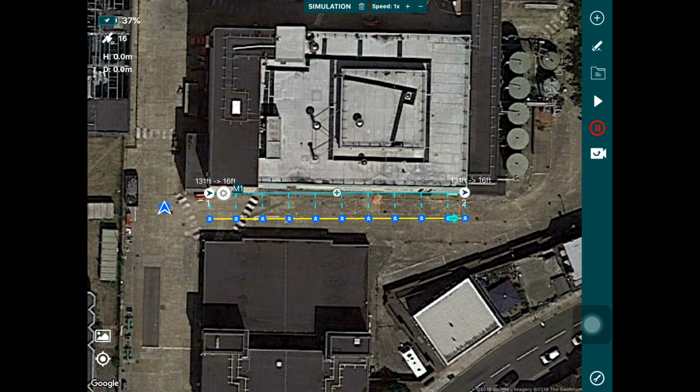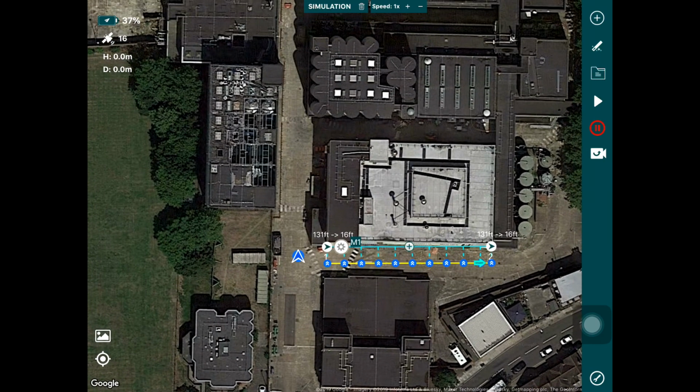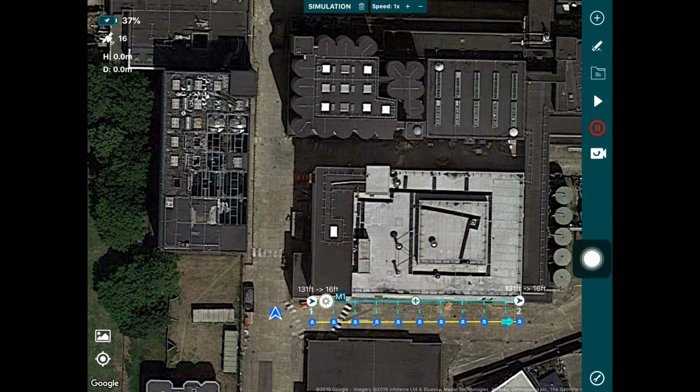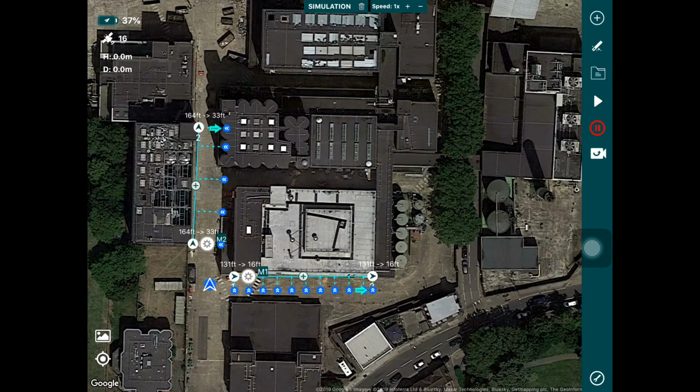Now, for the purpose of this video, we're going to show you that you can actually set up multiple vertical facade inspections, and you can even link them in the same flight. So let's say we want to do this facade here, and we also want to do that facade there. So I'm going to choose vertical inspection as I demonstrated before. I'm going to generate the mission.